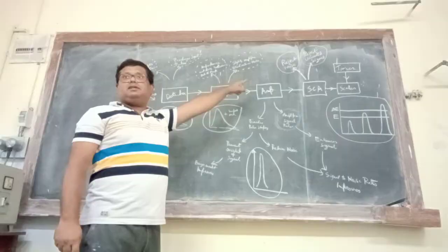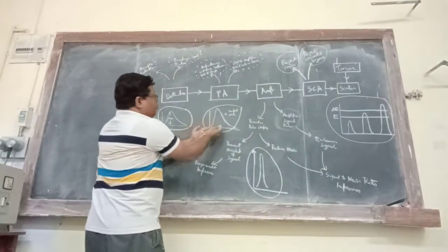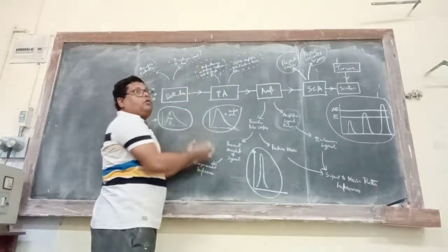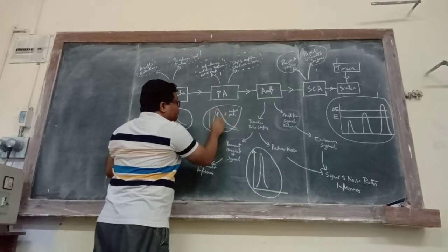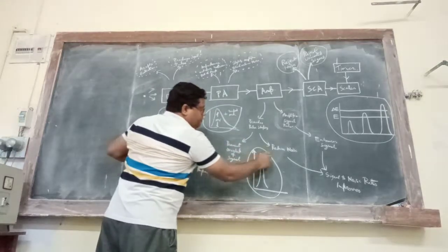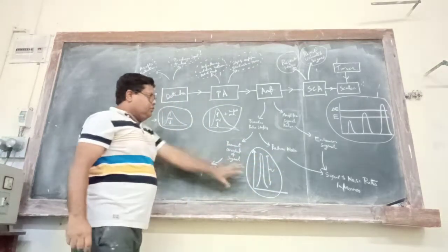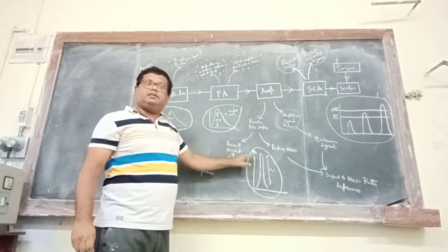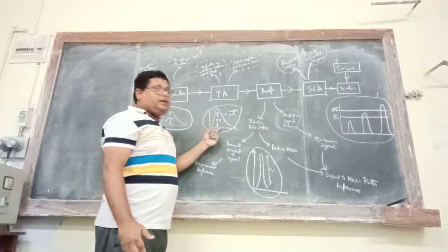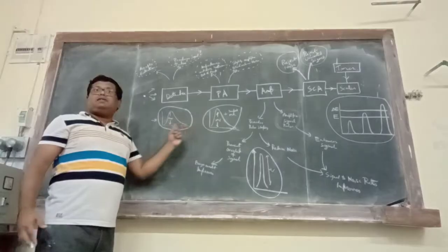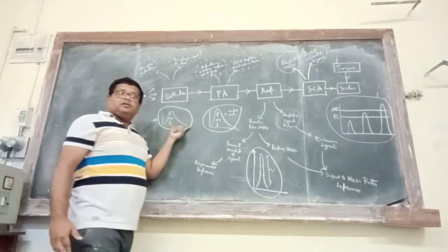Now let's see what the amplifier does. As the name suggests, it amplifies. That means it amplifies the y-axis more than 1000 times. So if the voltage is of the order of millivolts at the preamplifier, for the amplifier it will be of the order of volts or so. This is the amplifier pulse. Now look at the pulse. Number one, in these two cases it was asymmetric, and the tail of the pulse was very large, right?